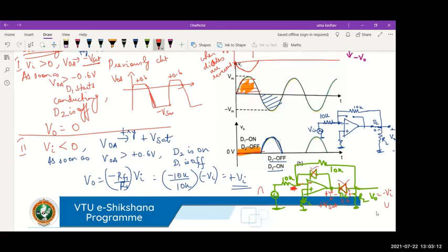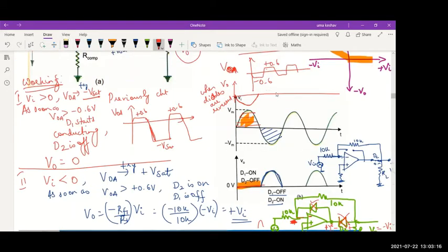Open loop here means the output becomes 0. So what you can see here is the output will be 0 for negative input, but it will be a negative value equal to the input in magnitude. So you'll have the same Vm for positive amplitude. Can you tell me how the transfer characteristic will look for this? What would be the transfer characteristics for this condition when both diodes are reversed?